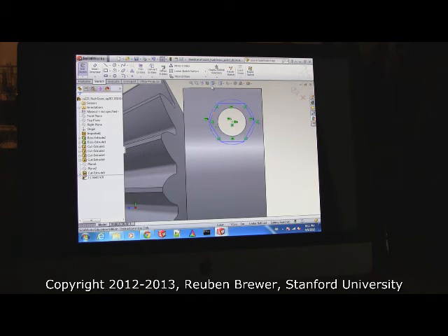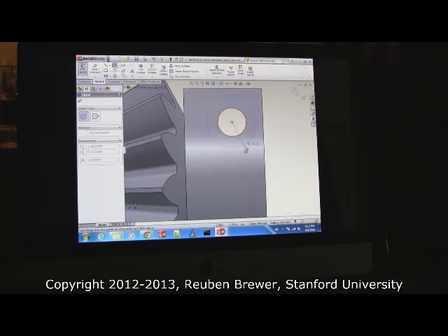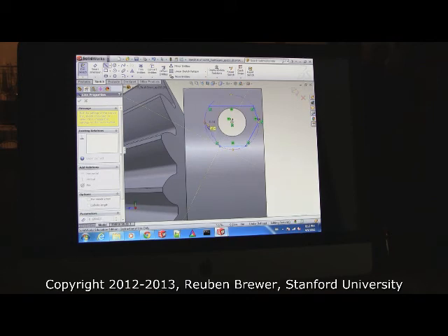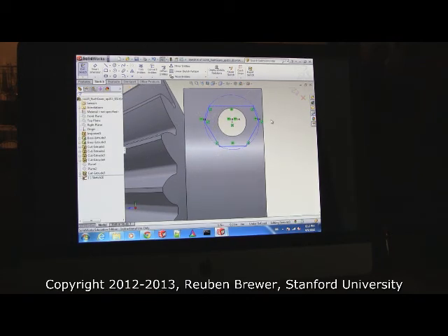Okay, does everybody's thing look sort of like mine? Would anyone like to see this again? Okay. So I take a circle like this, and I hit for construction. Okay, escape. Take a line, put it up here at about a 45-degree angle, and do horizontal. Now go down to this point here. It'll auto, see how it highlights it? Now go down somewhere else, horizontal, up here to that point that auto corrects, and then here. It's ugly, but can you see that if we made all of those lines exactly equal, it'd be a hex?